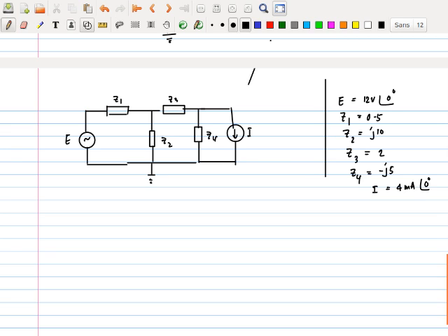So here you are. No problem, I'll use the same sort of technique. This is a node. I don't need to have a node here, because I can take this voltage minus that voltage to find the current that is flowing over here. This whole thing is obviously going to be a node, because it is the ground of the system. So I'll put this as node 1, node 2, this is node 0.